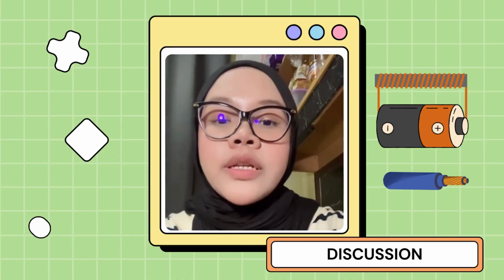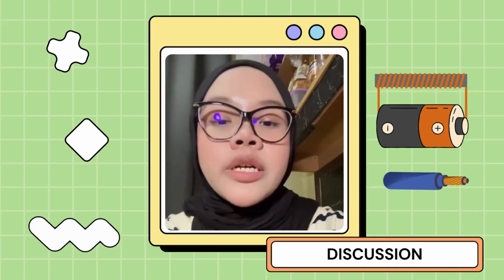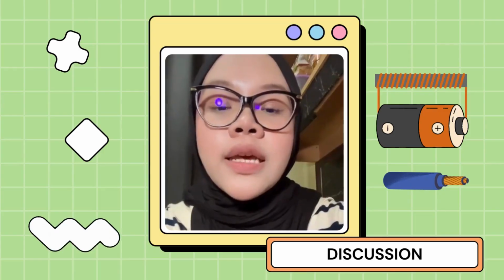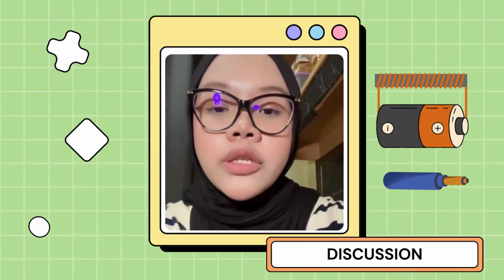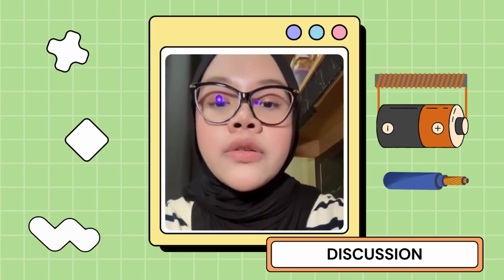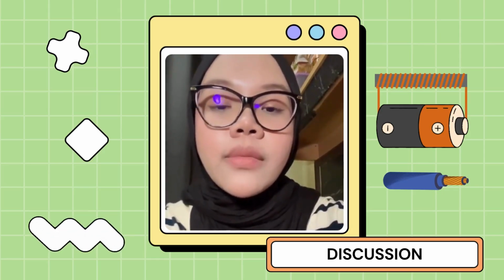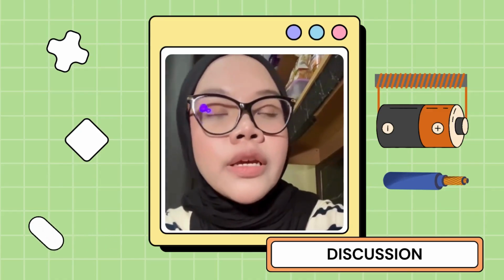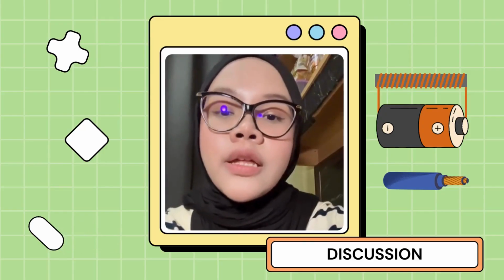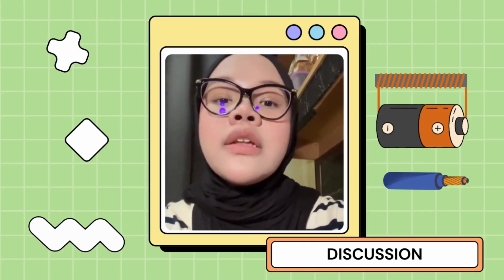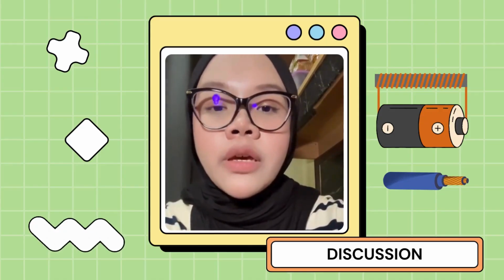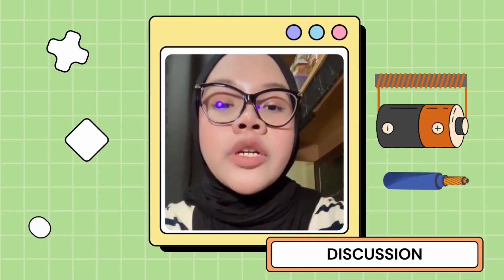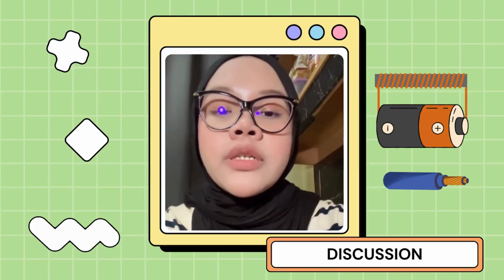The second one is apparatus limitations and systematic error. Firstly, the scale couldn't detect or display the small incremental change in force, such as the difference between sets. It likely has a measurement threshold, causing it to report a consistent average value. And secondly, the values like 13.8 newtons, 12.6 newtons and 12.2 newtons indicate the setup's self weight was significant compared to the small 2 newton loads, potentially overshadowing the subtle variations in shear force.